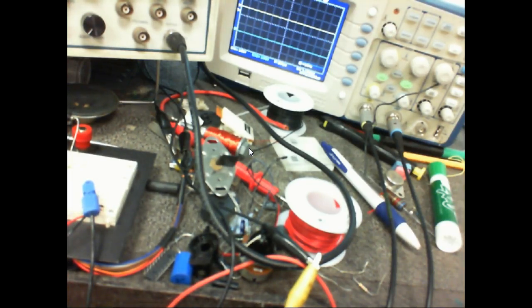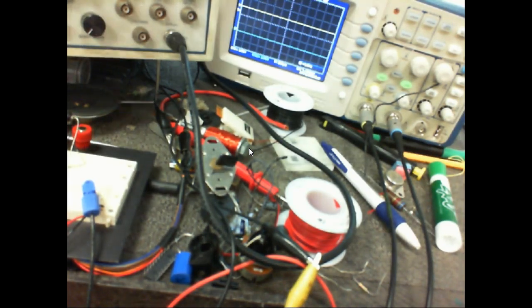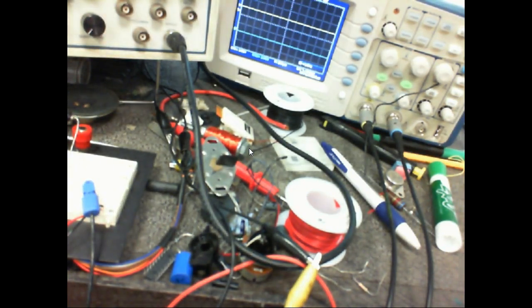These guys work off the voltage that's being induced into my body. They use little capacitors, and these are called capacitive screens. They have a matrix of thousands of little capacitors, and when you touch it, it uses the interference in my body, just strictly because of EMI being induced into my body, to trigger these to indicate a location. So this is why if you hit them with your fingernails, they don't work.